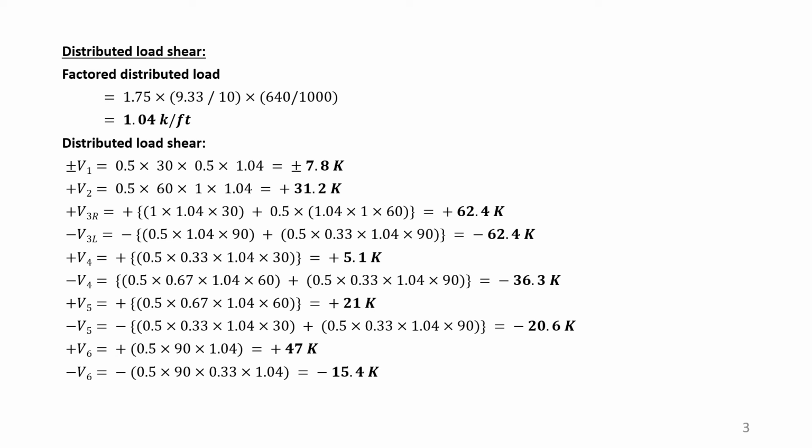First of all we have calculated the dead load shear. As you know, in the previous lessons you will see that there are shear values at different selected points for dead load. And in the previous lesson we calculated and showed the shear values for wheel load, and now we have calculated the values for distributed load, and now we will combine all these three together to get the final design shear value, the shear chart.